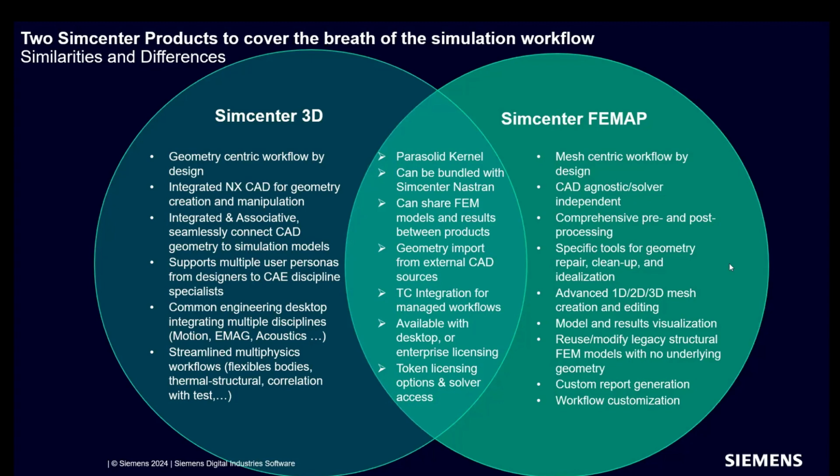But if you were to try to remesh that, like I said before, you'd have to somehow create some geometry based on that mesh. There are some tools in Simcenter 3D to do that. You can skin the mesh with a geometry surface and then associate that surface back to the mesh. It's just extra work that is required.